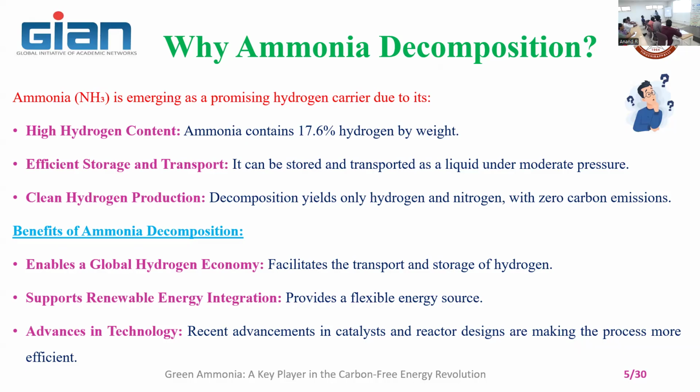Apart from that, people are also using membrane technology to break down ammonia into nitrogen and hydrogen. There are temperature based membranes, and pressure based membranes, like PSA, but you can also use catalytic coating membranes. You are able to convert the ammonia into nitrogen and hydrogen.